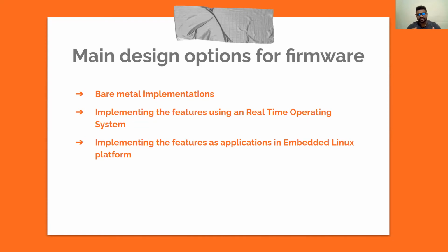So there's another class that is running directly on the microcontroller, and they are called bare metal implementations. We use that if our design is very small and straightforward to implement; most of the time we go for a bare metal implementation. And there's another paradigm, implementing the features using a real-time operating system. There are many in the industry at the moment. One of the free ones is called FreeRTOS.